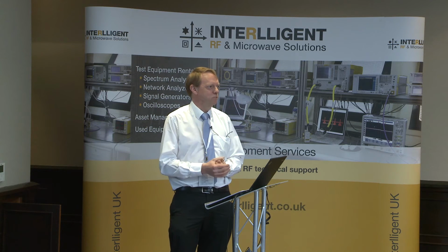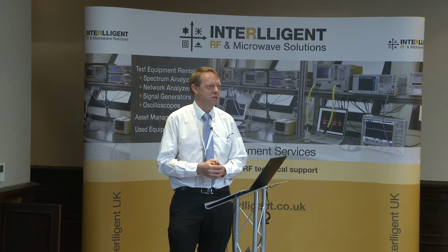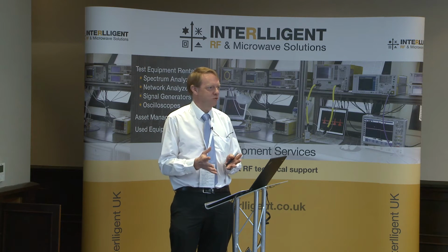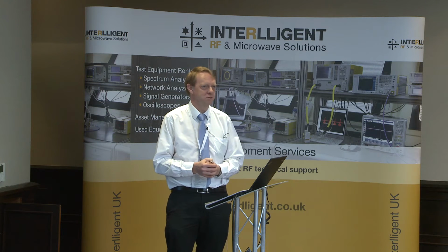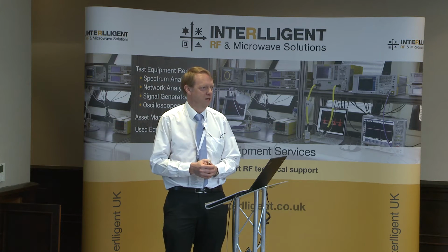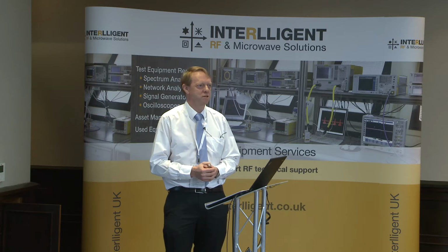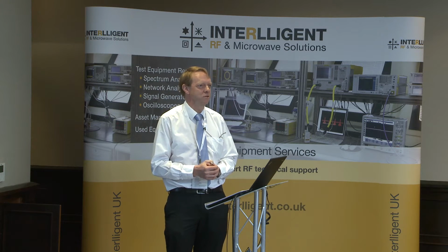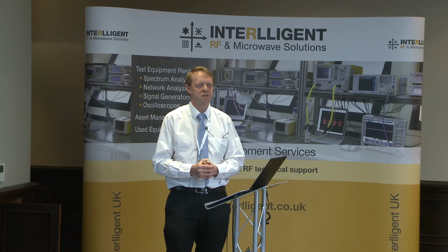But certainly, to make it a reliable product, use all the components well below their rated limits, so maybe a factor of 0.5 on derating voltages and power dissipation and current consumption, this kind of thing. It can be a tedious thing going through an entire circuit, making sure that every part is not straining within an inch of its life. But that does make a big difference to the yield of a product out in the field.